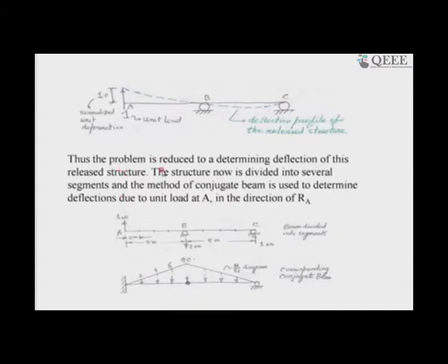The problem is that we have avoided the real issue which we had at first principles, that is, let the unit load move, take the rigid body, draw the free body, and from there find the solution for the different stress resultants. Those we are not doing. We are already with the Muller-Breslau principle. We have got the qualitative shape of the diagram. Now, it is left to us to determine the quantitative values, and the problem is reduced to determining the deflections of the released structure.